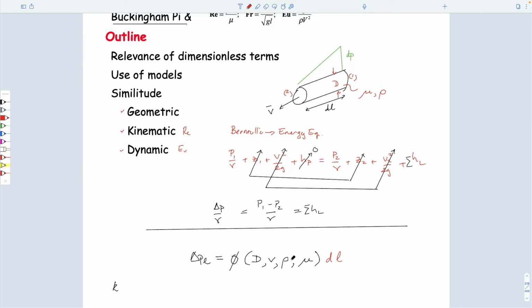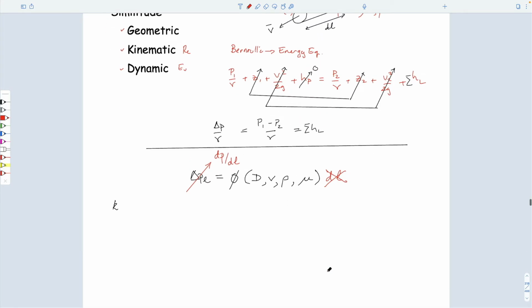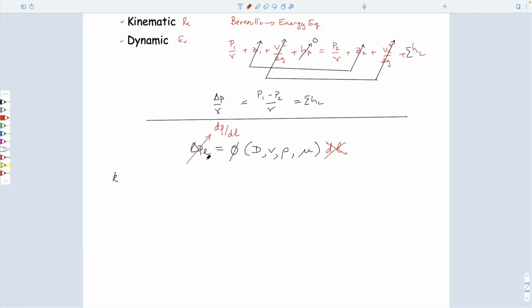You see all these mentioned here. The length would also be 1, except in the book, and just to make this an easier condition, this parameter here is pressure change with length. And so if that's the case, then we don't need to have this here. And so we just need to be cognizant of the fact that this delta PL is a pressure per unit length.